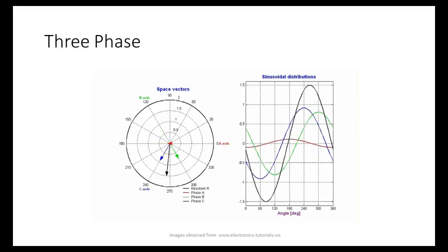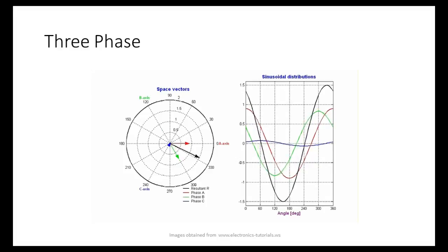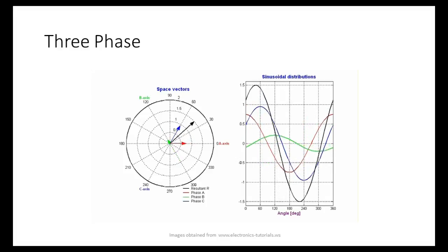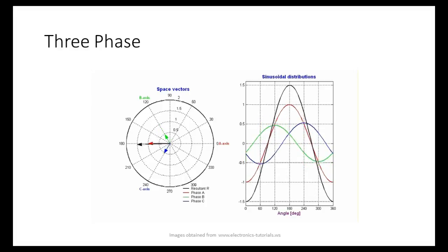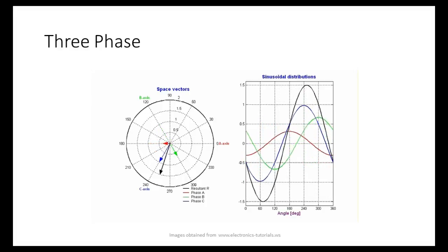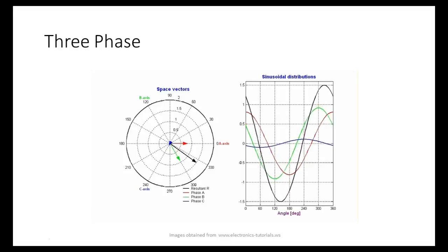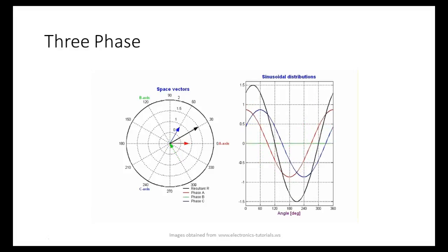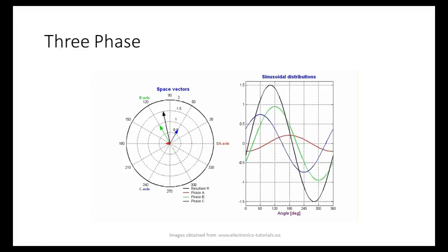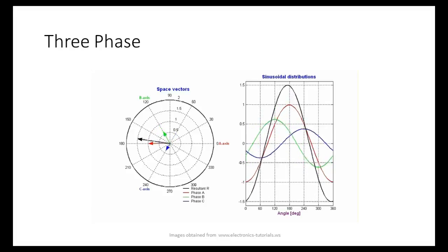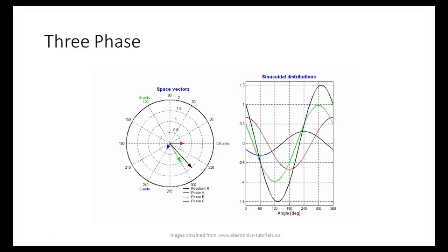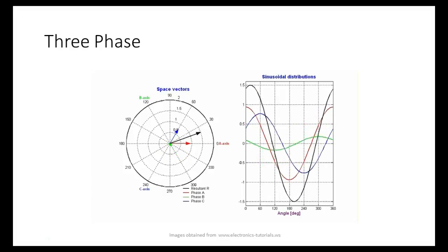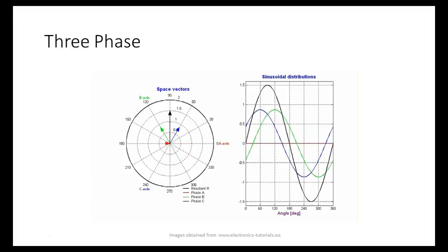Yes or no? It's just like on your house. You should stagger your circuit breakers on your house, so you won't overload one side of your transformer out there on your pole, your single phase. Your 240 loads, you don't worry about those because those are on both sides of the transformer. Your 120 volt loads are either on one side of the transformer or the other side. Understand what I'm saying?